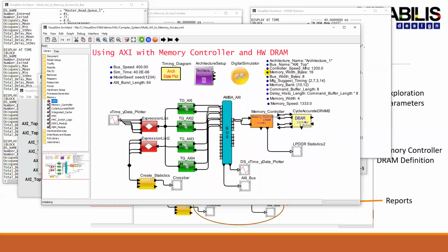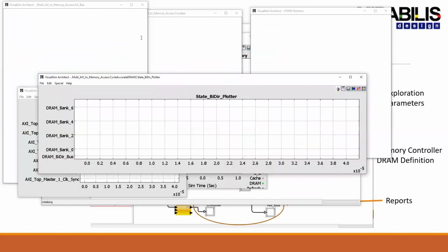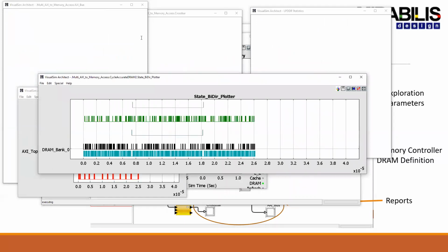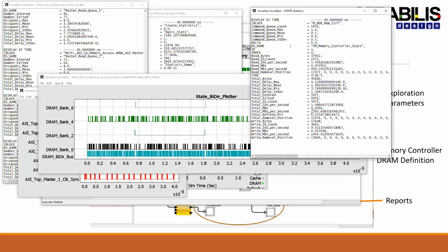So now we're starting to change the memory controller. Until now, we were trying to see how much more the existing architecture could handle. Now we're making the memory controller significantly faster, trying to see if we can get better performance there. Also, we're changing the scheduling to add more reads before I jump over to a write, to see how that changes the performance.